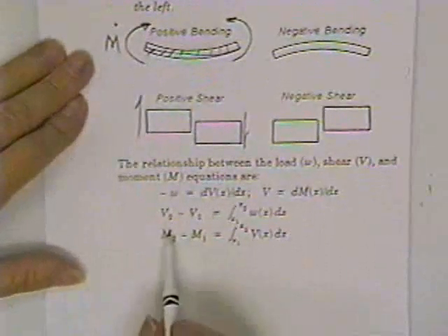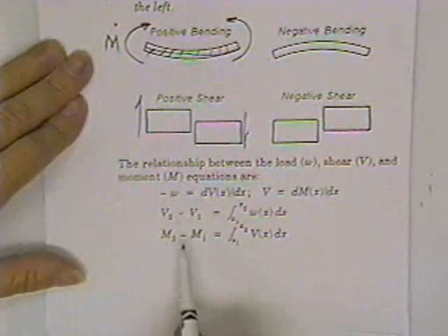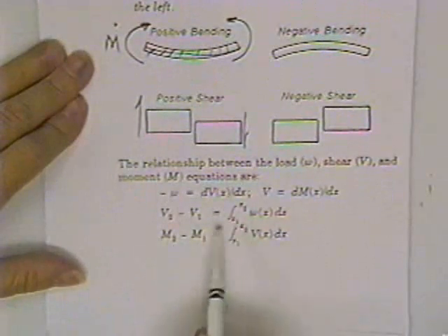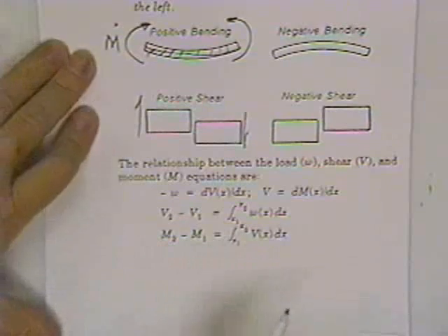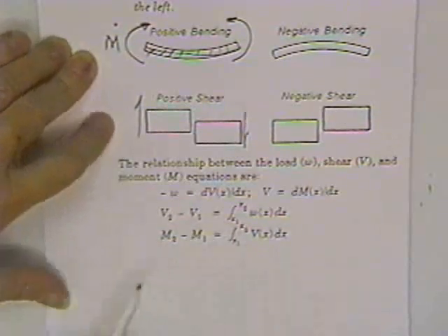There is a relationship between load, shear, and moment. And all you got to do is you integrate the load, you get the shear, you get the change in shear. You integrate the shear, you get the change in moment. We'll show you how to use that in a minute.